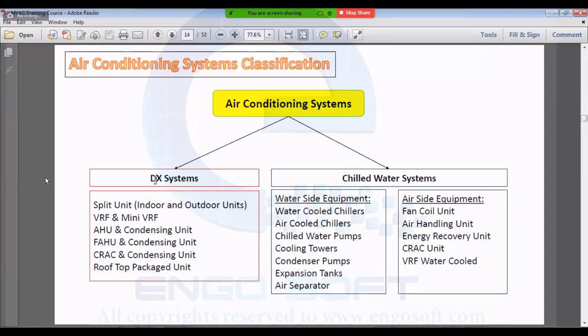Okay, so I will cool 100 liters per second from 46 degrees to 24. So what is the cooling load? The cooling load will be the flow rate, which is 100 liters per second, multiplied by the heat capacity, multiplied by the delta T, which is 46 minus 24. This is the cooling load.